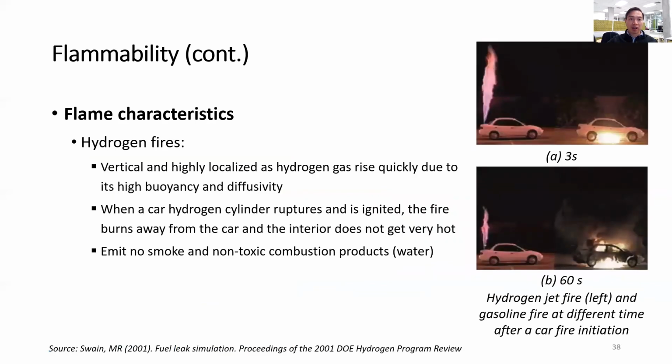The hydrogen fire, when compared to a gasoline fire, is a bit different because of hydrogen's ability to quickly rise due to high buoyancy and high diffusivity. The hydrogen fire is normally a vertical fire and highly localized. So when you have a hydrogen cylinder ignited in a car, the fire is going to burn away from the car, and the interior might not get very hot compared to that in the gasoline case.